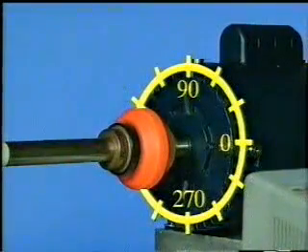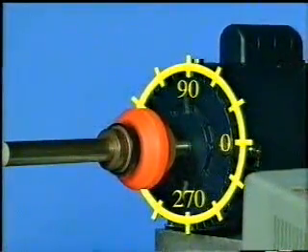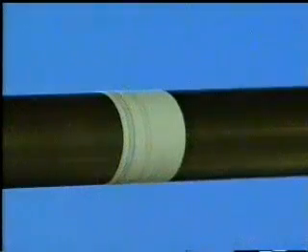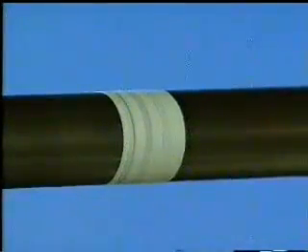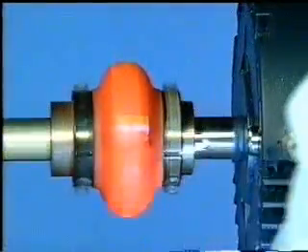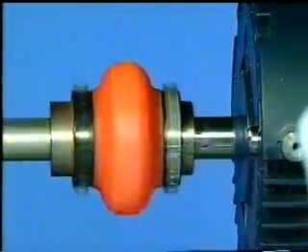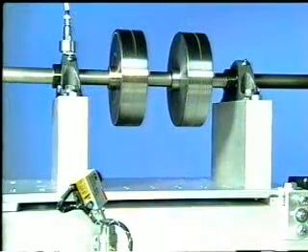When the rotor has a reference mark, then the phase angle must be read from stationary marks from 0 through 360 degrees. When the rotor is marked with the angles, then use a fixed point on the machine as the reference point. Then, as the sensor is used to roam the machine, the phase angle can be read directly from the rotor and the machine, and then manually recorded. Whether you use a strobe or a photo tach and analyzer, the rotor must be marked. For most of our examples, we will use the photo tach and an analyzer.